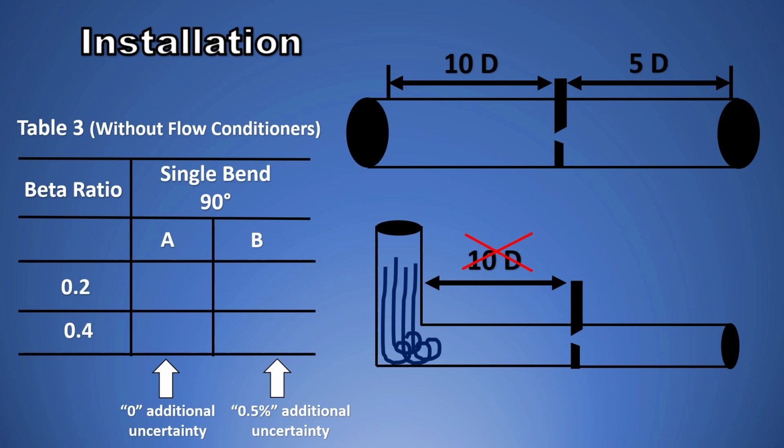For example, if it is water, you might not be that strict, right? So for example, in the A table, if the straight run requirement is 6, for B it is 3, so 3 diameters upstream is the requirement. Similarly, there would be values for the downstream in the table. Now here, for A you require 16 diameters upstream, but in the B table again 3 is okay for you. This is how you can read this table in ISO 5167.